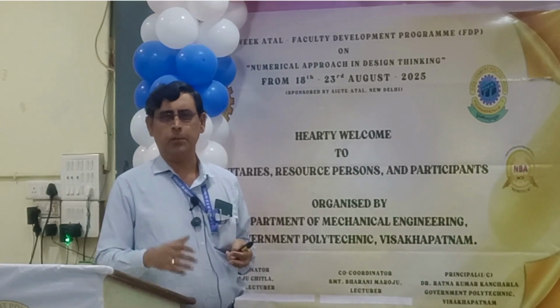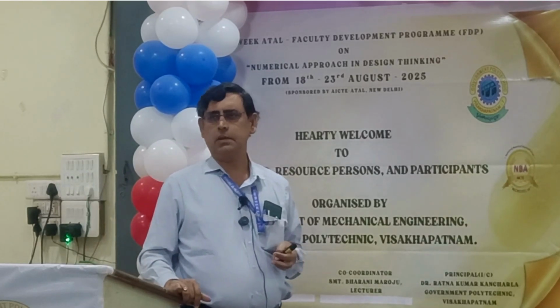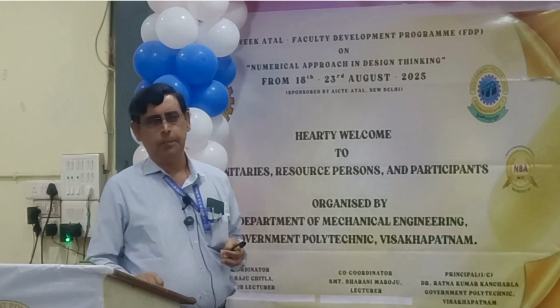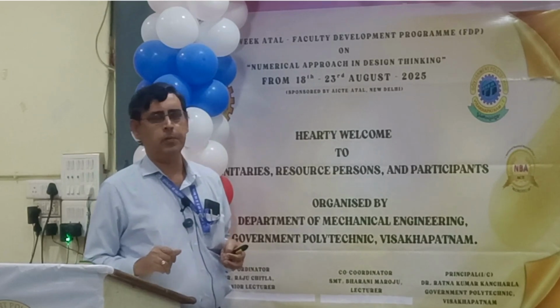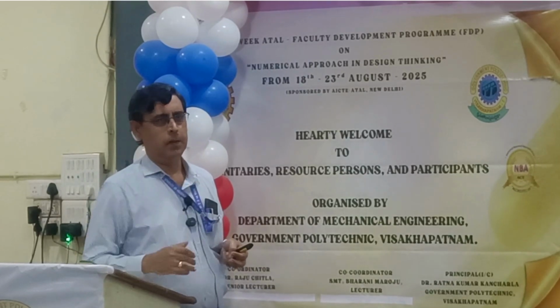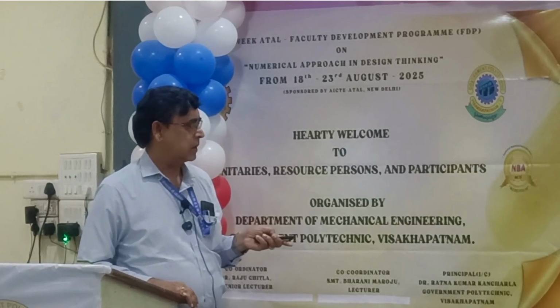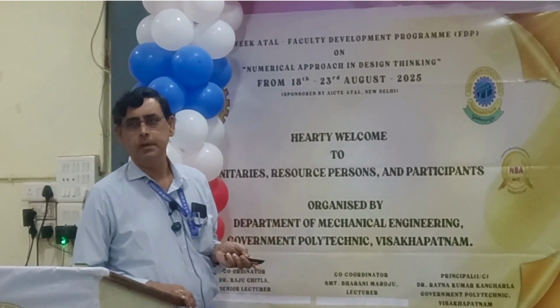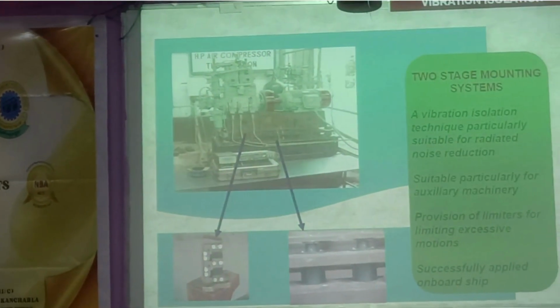Or even the natural frequencies, etc. We have modal analysis in the FEA. We have frequency response analysis. We can do all those. But then the response analysis is only applicable to certain frequencies because of the limitations in the finite element method. So that is why we need better, higher methods like statistical energy analysis method. Okay, so that is one thing.